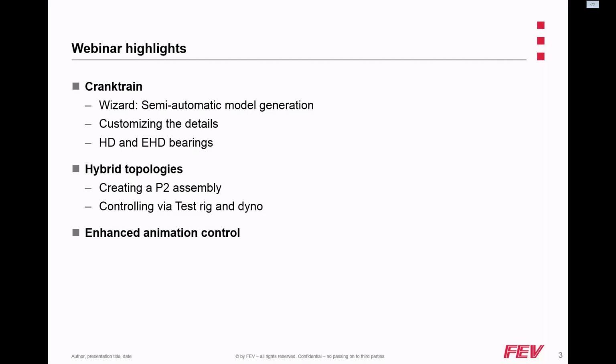So this question would be more related to when I select the user option. In this user option, you want to calculate using a constant stiffness, which may be beneficial in some cases. In this case, either you get the values yourself, otherwise Virtual Dynamics also provides an estimation tool. This estimation is done based on empirical formulas, which are derived from ISO standards, and also it is based on our expertise. So the stiffness, either you need to know it by yourself, or you need to calculate using an FE software, or the best option available to you would be to use this estimate button, which is the stiffness provided by Virtual Dynamics. I think this sufficiently answers the question.